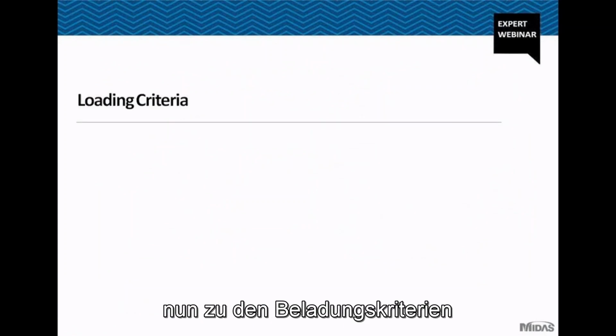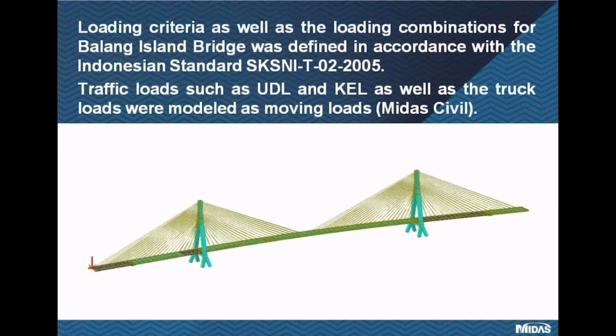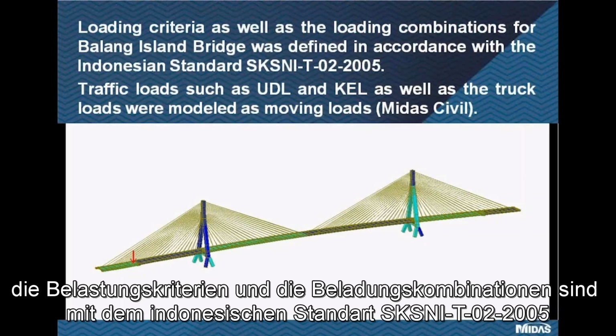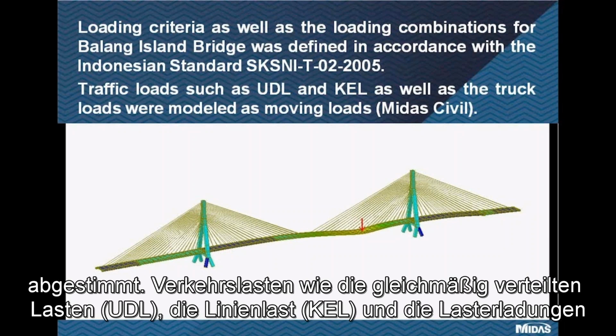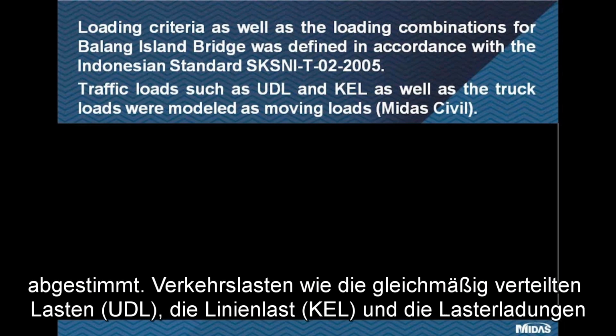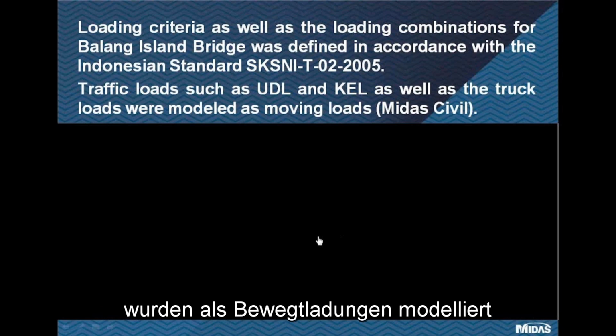How about the loading criteria? The loading criteria as well as the loading combinations for Balang Island Bridge were defined in accordance with the Indonesian standard SKSNI T02 2005. Traffic loads such as UDL or Uniform Distributed Loads and KEL or Knife Edge Loads, as well as the truck loads, were modeled as moving loads.